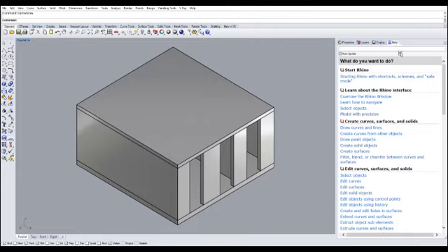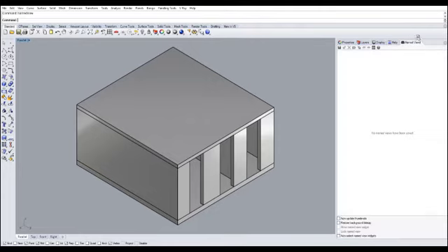If you want to put it back in there, all you have to do is just drag the tab. Right now, this view has not been bookmarked. To bookmark your view, make sure your name view is open, and then there's a save as icon. Click on it and let's call this diagram A. Now that view has been bookmarked, this perfectly nice and centered view is bookmarked.